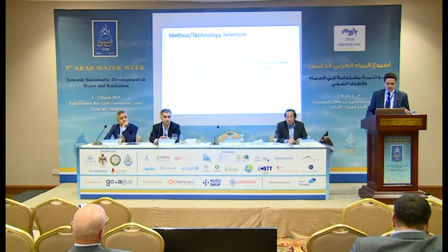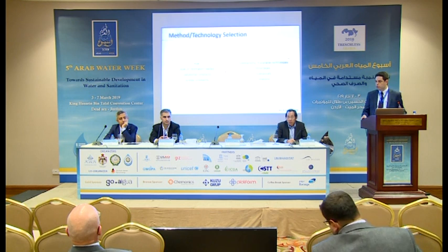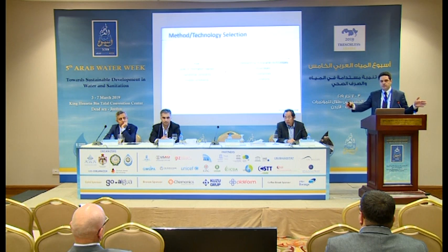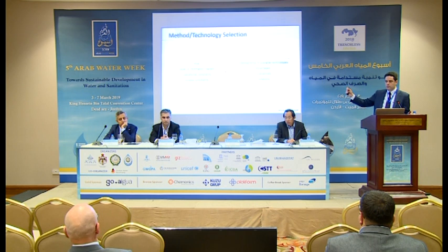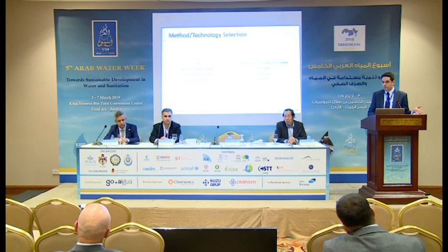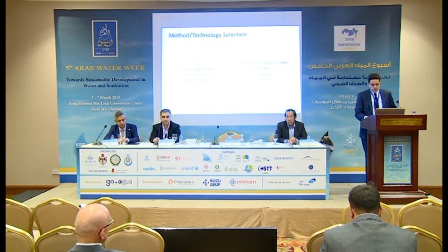And then the next question is the method and technology selection to do the condition assessment, which basically depends on two sets of parameters. The first one includes the risk that you just identified previously, and the level of information that is needed. Are you looking to get a general sense of the pipeline condition, or do you actually want to know every single wire break, pre-stressing wire break, along the pipeline? What operational constraints do you have? Can you shut down the system? Can you dewater the system? Or do you have to inspect the pipeline in service and so forth?